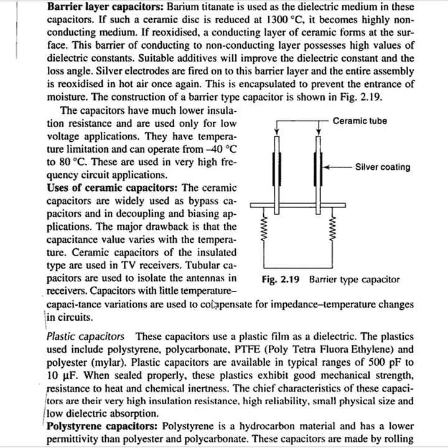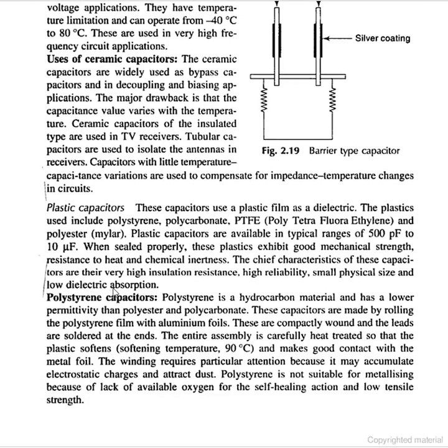The capacitor uses a plastic film as a dielectric. The plastics used include polystyrene, polycarbonate, polytetrafluoroethylene, and polyester. Plastic capacitors are available in typical ranges of 500 picofarad to 10 microfarad. When sealed properly, these plastics exhibit good mechanical strength, resistance to heat, and chemical inertness.